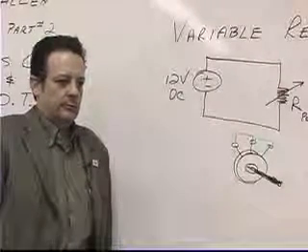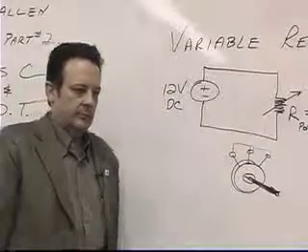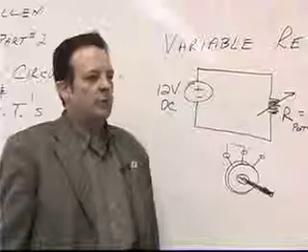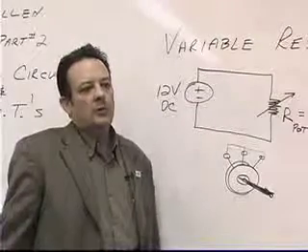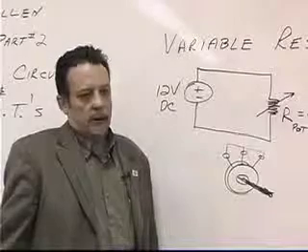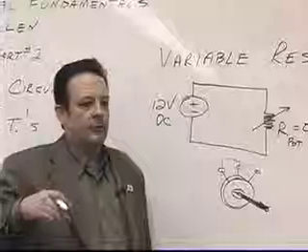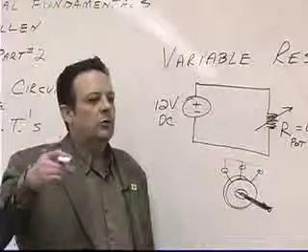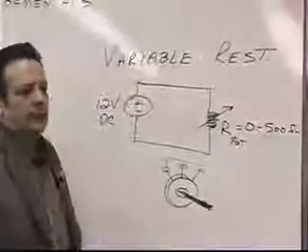Short circuit. Would it be the plus or minus kind of thing? Okay. The way that it works with a potentiometer is if you connect the outermost leads together and then you connect the potentiometer in series with the rest of the circuit, you are going to get the maximum value of the potentiometer.